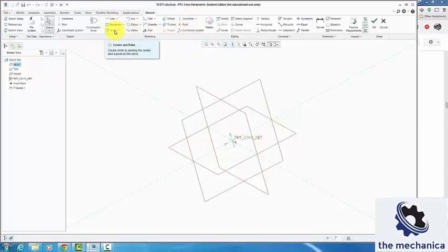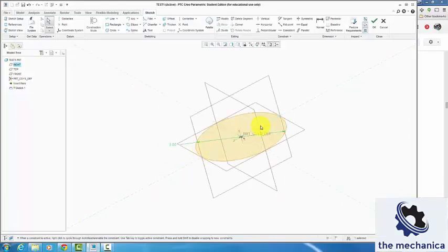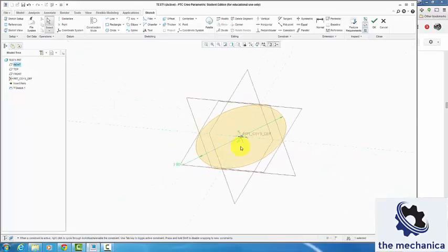If I want to draw a cylinder, I would draw a circle, start at the center, bring it out, and click. And if I hit escape or middle click, I get this. And so it's giving me what size that is. Don't worry about drawing it the right size when you're starting. You can add that in. So if I double click on this, I can change that to be 3 inches. It resizes it and rezooms me in. So I can pan around and see that.